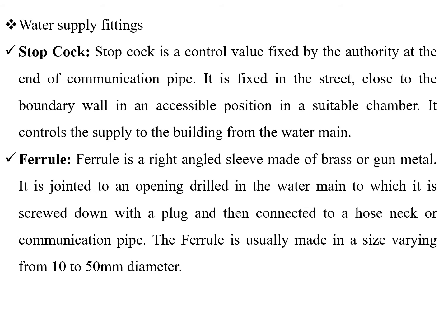Water supply fittings. Stop cock. Stop cock is a control valve fixed by authority at the end of communication pipe. It is fixed in the street close to the boundary wall in an accessible position in a suitable chamber. It controls the supply to the building from the main water line.